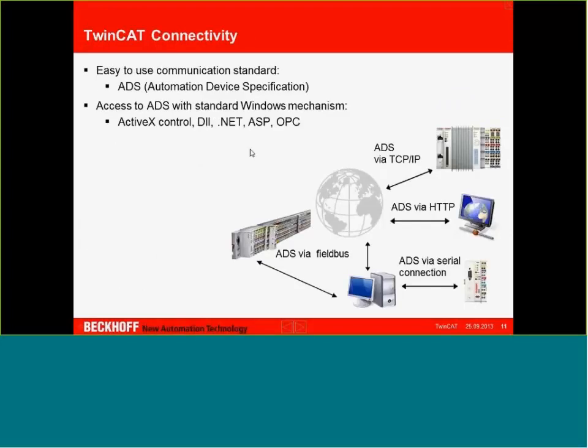And look at TwinCAT connectivity. Everything we do as far as communication, under the hood, if you will, is all based on ADS, the Automation Device Specification. This is not a Beckhoff-invented communication protocol, but it's something that we do use. So under the hood, regardless of what language we're actually talking, what field bus we're actually talking, when it comes back to the PC, everything's done over ADS. So you see in the diagram here, ADS is the main hub of the system. It's basically an ADS router that talks out to all the peripheral devices.